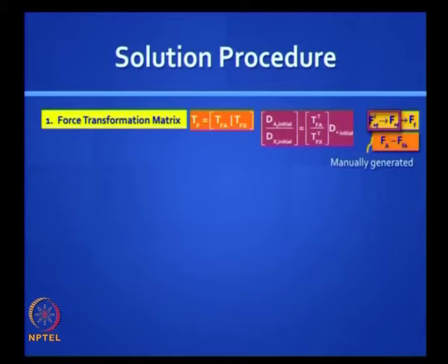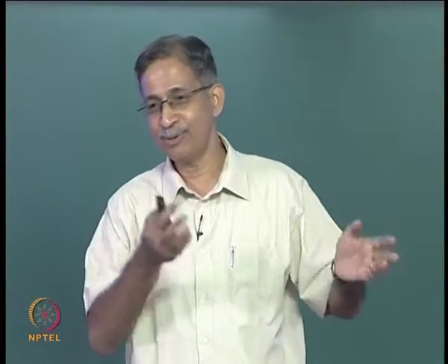The procedure is exactly the same, only thing here, it's a pity that you have to borrow a stiffness method idea to deal with distributed loads, because there is no other way you can handle it in a matrix framework. So you have to find out fixed end forces, which means going back to stiffness, borrowing that concept from stiffness method.